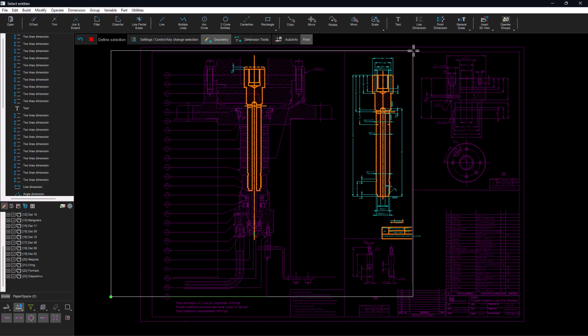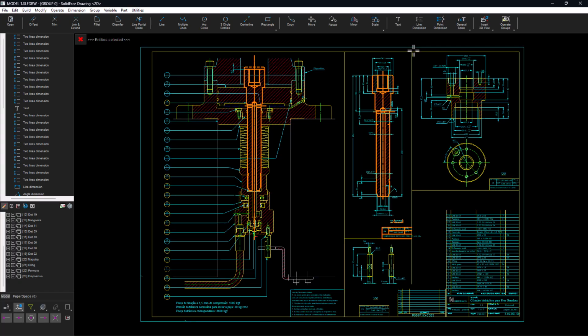As already explained, each group has its own list of commands. When creating an entity in an active group, you can use geometric information, midpoint, extreme, etc. from any passive groups. However, when referencing geometric information from passive groups, this information is not auto-associative. In other words, when modifying an entity in the active group, this modification will not be automatically associative with the geometry that referenced it in a passive group. Auto-association will always be possible in entities created in the same active group.